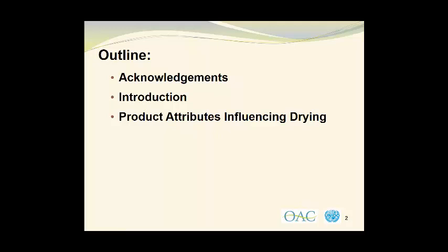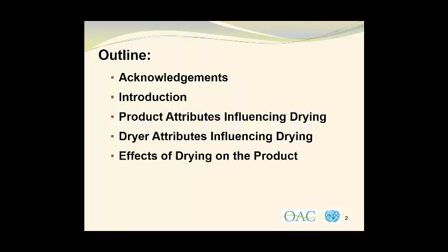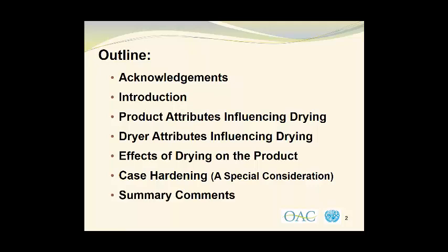We'll look at product attributes that influence drying and follow this up with the dryer attributes that influence drying. And we'll examine the effects of drying on the product and look at case hardening as a special consideration. Then we will close with some summary comments.